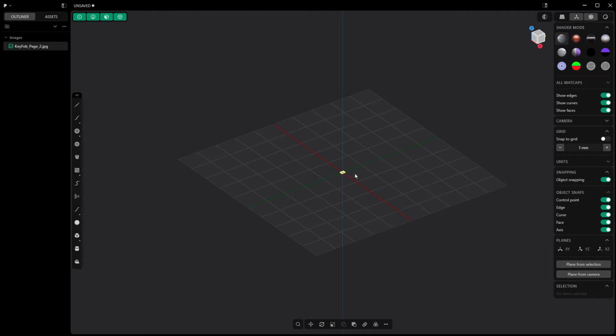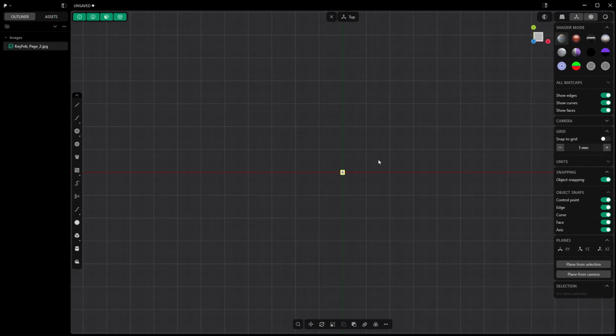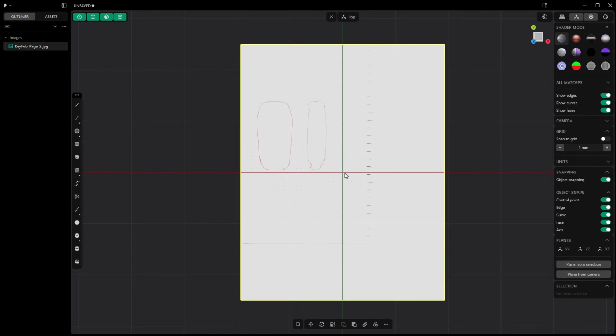The first thing that I suggest we do is get to a construction plane, because when we start to create new curves, lines, splines, arcs, and things of that nature, when we have an active construction plane, this means that the geometry is going to snap to that by default, and this is going to help us make sure everything's in the right location. So in order to do that, let's first go to a top view by clicking on the top of our view cube. With our object selected, I'm going to use /, which will zoom into it.